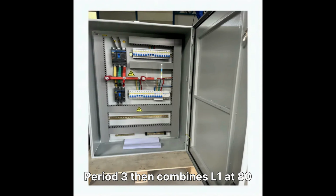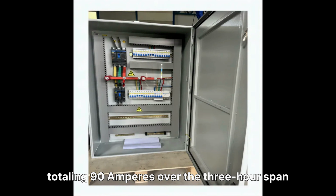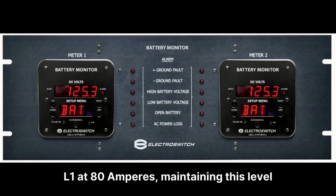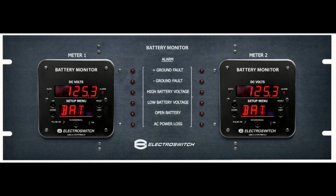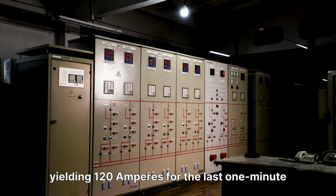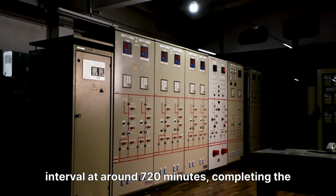Period 3 then combines L1 at 80 amperes with L3 emergency at 10 amperes, totaling 90 amperes over the 3-hour span from 180 to 360 minutes, ensuring backup for critical functions. Period 4 returns to only the continuous L1 at 80 amperes, maintaining this level until the final restoration phase, underscoring the baseline requirement for the battery. Finally, Period 5 combines L1 at 80 amperes with L4 restoration at 40 amperes, yielding 120 amperes for the last 1-minute interval at around 720 minutes, completing the duty cycle.